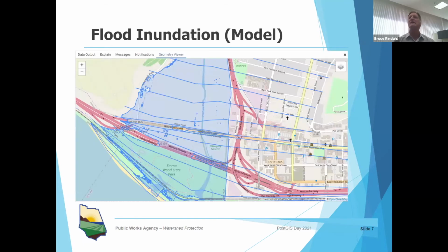To give you some idea of what this is, typically this is a cross section at all these various locations. The model takes the flow and generates an elevation at each cross section. This comes from HEC-RAS, HEC-2, for those of you who are involved in flooding systems. We want to convert those elevations at the various cross sections into a continuous elevation to get some kind of a boundary. Now, this is the first step. We'll take the inundation boundary model and the cross sections at various locations, and then do a smooth interpolation between the cross sections.